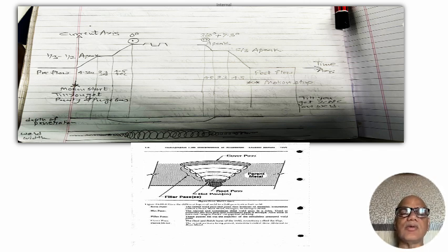And this is the way you continuously move it, and all these possibilities are explored for every run. You make a separate program right from the root run, to the fill up runs and to the cover up passes, and accordingly you are getting for every run, every pass, a different characteristic that you desire between voltage, current, upslope, downslope, pulsing, non-pulsing, frequency, high frequency, low frequency, and you achieve the best weld.